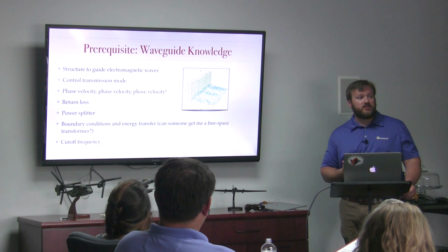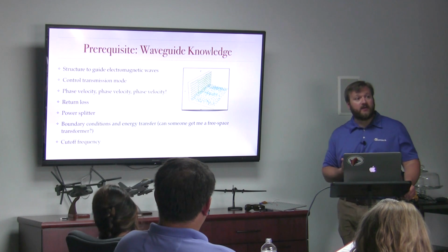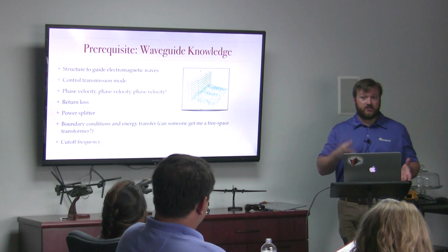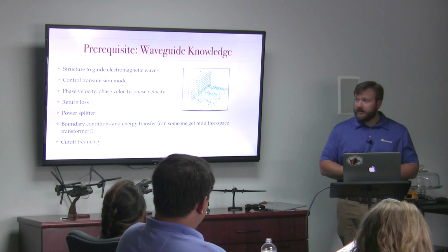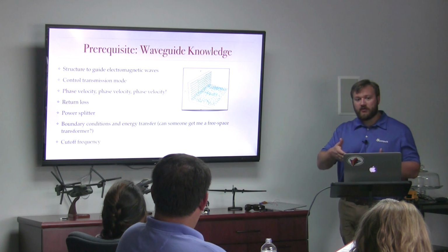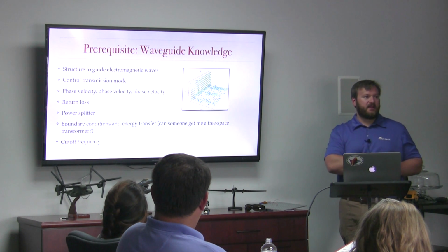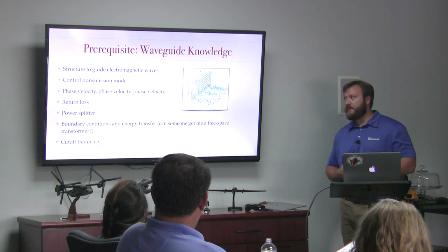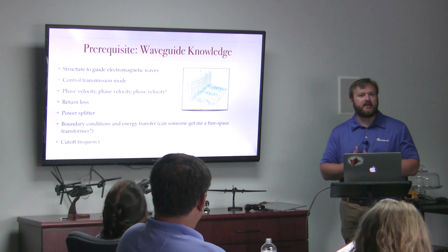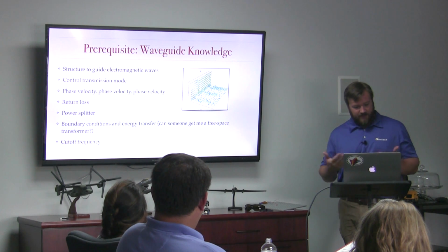Now, something interesting is you can have higher order TE or TM propagation modes going down the waveguide. In a larger waveguide, you can push higher frequencies. You just will be changing transmission modes. Now, part of something else that you need to look at is you always have a cutoff frequency. There's always going to be a minimum frequency that can maintain a transmitting mode of propagation down a waveguide. For the one we're using that's actually feeding the antenna, that ends up being just under 8 gigahertz, where the cutoff is. But there's a fair bit of insertion loss you're coming with at that point.